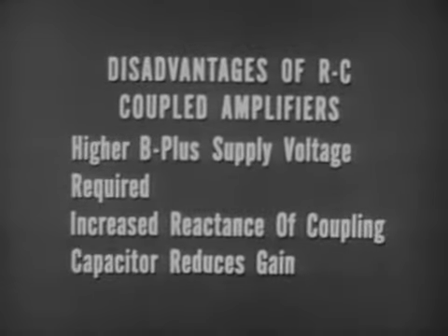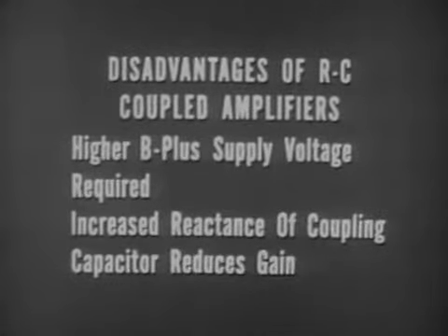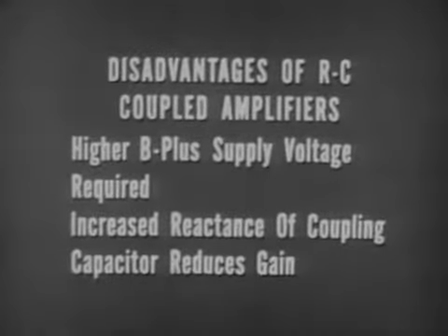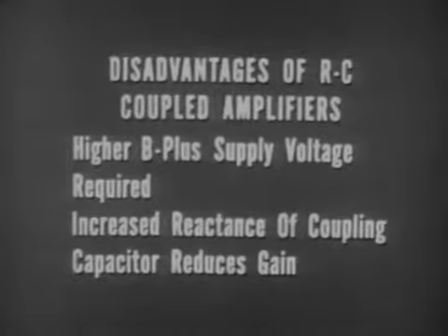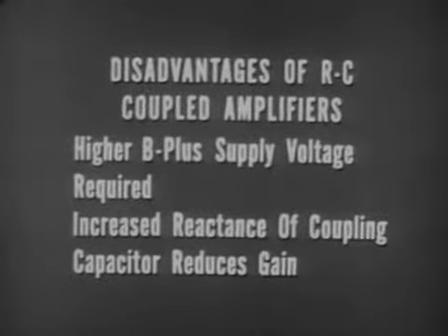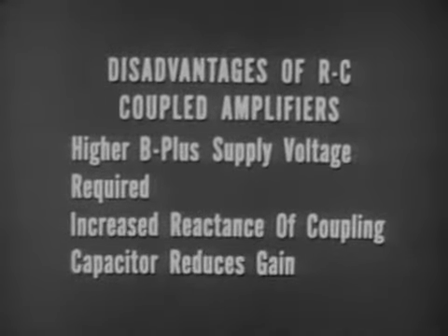The disadvantages of RC coupled amplifiers are that a higher B-plus supply voltage is required, and the reactance of the coupling capacitor increases at lower frequencies, thus reducing the gain.